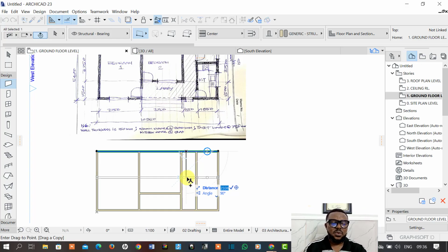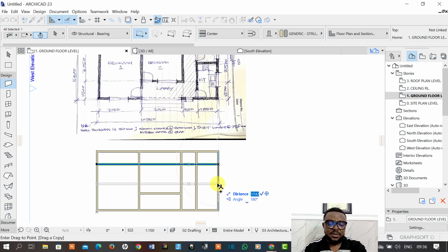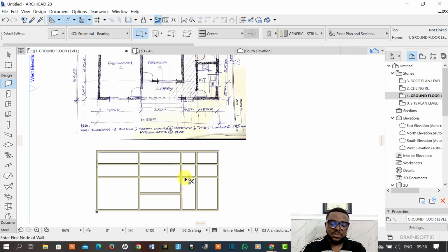So where are we taking it to? We want to offset to create the toilet, and the toilet center to center is 1150. Enter. In to in is 1 meter. So you have the thickness of the wall 1150, and that's the same thing that we need for the next one. So we repeat that action again. Control D, Control, drag, Shift R, 1150, enter. That's it, and we have them ready, so we can cut off.